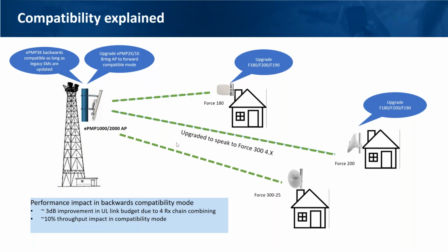Next question was, when using the MU-MIMO ePMP 3000 antenna, if there is a mix-up of radio to antenna RF ports, does it have any effects on transmission? Yes, it will have impacts. We did label everything. We need the horizontal, vertical, 1, 2, or 0, 1, 2, 3 to go to the corresponding ports on the antenna. And I think we got it right first time around in terms of labeling it. So yes, we do want that to be accurate.